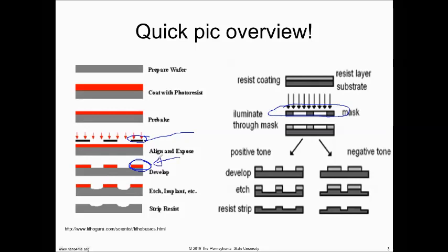I don't know why somebody didn't invent 2 different words, or why people refer to them the same. So these are both called a mask. This is a hard mask, used in manufacturing. And this part right here is my masking agent, my photoresist once it's patterned. Then I could use that as a mask for etch or implant or deposition at that point. So that's my temporary mask, and I'm going to strip this off later on. This thing up here is my hard mask. Does that make sense to everybody?